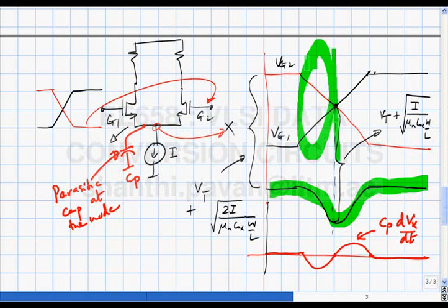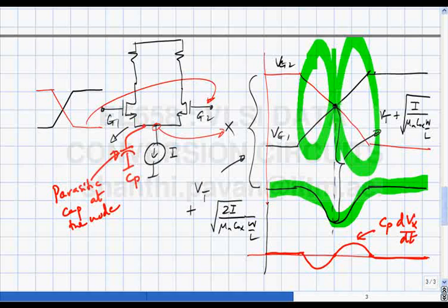Does it flow towards the left or the right? It flows towards the right. During this half, it flows towards the left. The exact fraction hardly makes sense to compute because we are doing such an approximate analysis. Ideally, we would expect the current to just switch from the left leg to the right leg without you being able to notice anything.